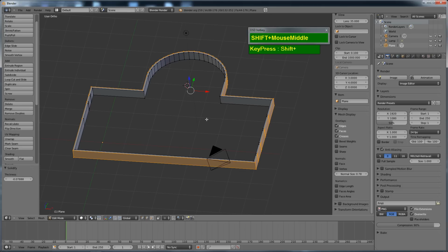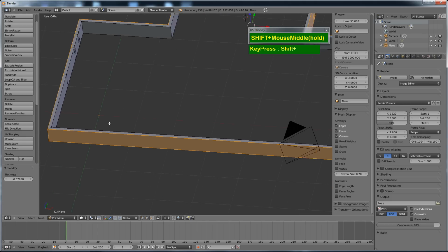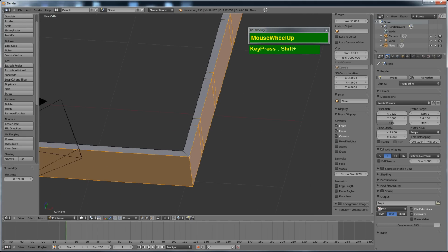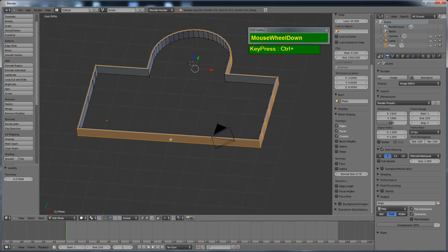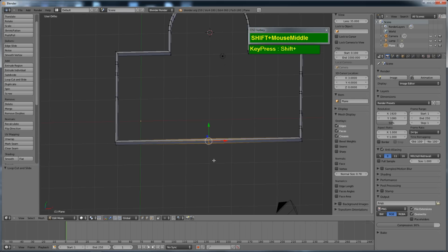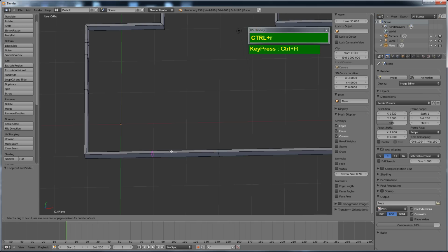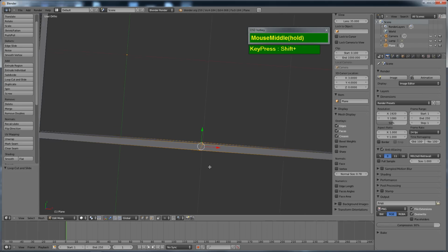So then how do we create the windows? We already know how to create the doors, but the problem with using this method is this. If you look at the corner here, there is a 45-degree angle, and if I insert one edge loop here, at the center it looks fine, it is perpendicular, 90 degrees. But let me insert another edge loop here, Control R. See, as I drag the edge loop closer to the edge, it's going to bend. In fact, if I place the edge loop here, you can see that it is not perpendicular.